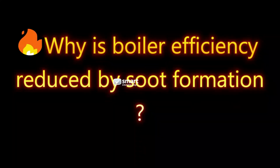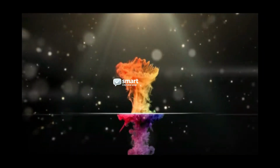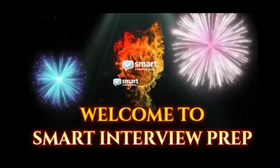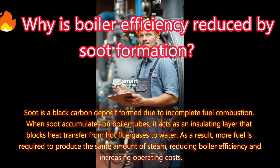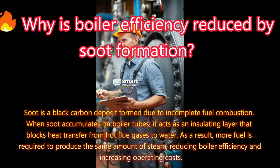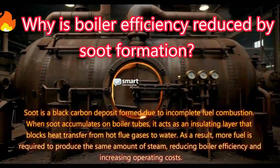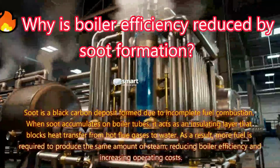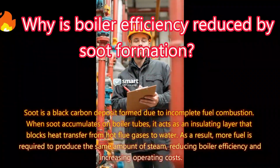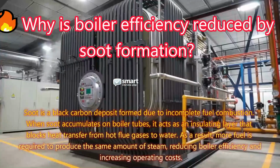Why is boiler efficiency reduced by soot formation? Answer. Soot is a black carbon deposit formed due to incomplete fuel combustion. When soot accumulates on boiler tubes, it acts as an insulating layer that blocks heat transfer from hot flue gases to water. As a result, more fuel is required to produce the same amount of steam, reducing boiler efficiency and